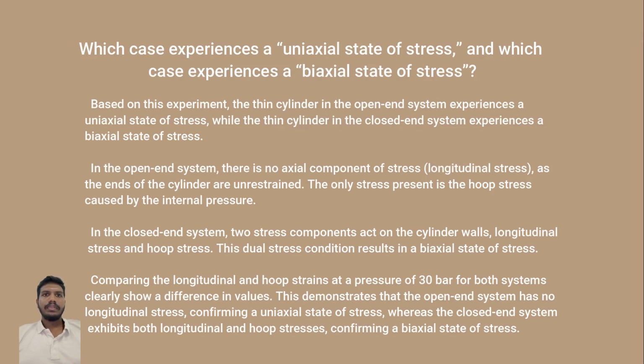In contrast, the closed-ended condition experiences a biaxial state of stress. With both ends sealed, the cylinder is subjected to two stress components, longitudinal stress and hoop stress. When we compare these two systems experimentally at a pressure of 30 bar, the difference becomes evident. The open-ended system shows no longitudinal stress, confirming its uniaxial stress state. Meanwhile, the closed-ended system exhibits both longitudinal and hoop stresses, validating its biaxial stress state.